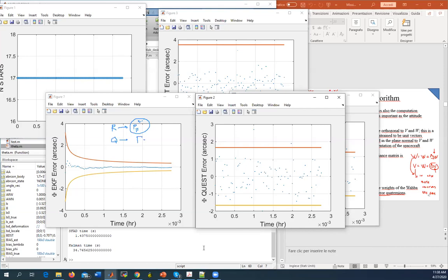He integrated that by assuming the matrix Gamma that is in the process noise appendix. Gamma, as I said, is the integral over time of the transition matrix that we have also seen, times G, the matrix that multiplies the effect of the gyroscopes over time. By including these two terms correctly, of course, you have a perfect tuning of the filter. You are probably not able to do that correctly by yourself, because R is straightforward, since you have the knowledge of R from the PQ, but it's a little more complicated to determine Gamma.